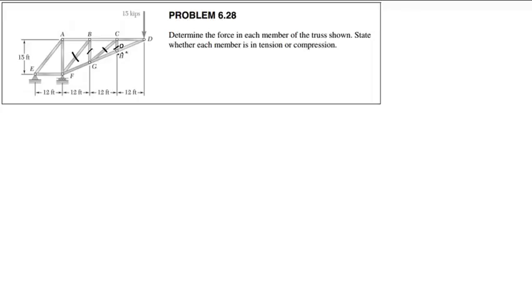But the kind of slender elements you make trusses out of, that's not going to work. You would need a ridiculously thick member here. You're not going to do that with a truss. You need something to brace that with. So that's what a lot of this stuff is for. It's there to brace the column, but not necessarily directly carry any load.